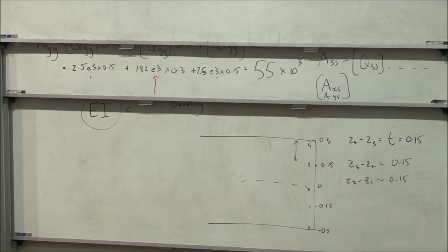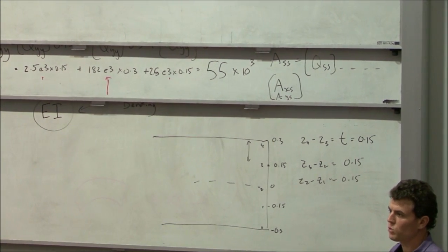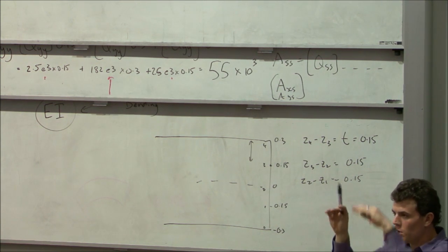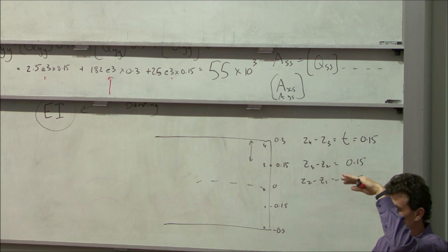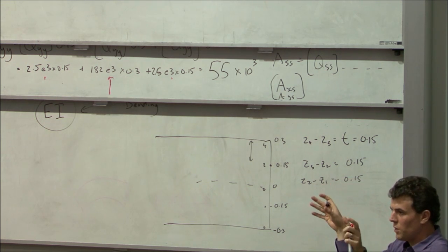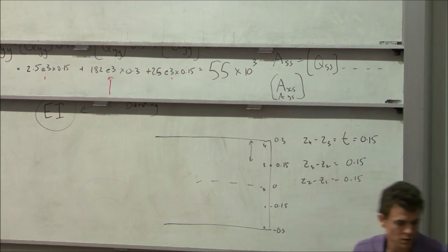So the contribution of them to the in-plane stiffness is constant. But in bending, we have to amplify the things that are away from the center. Just like when you make an I-beam, the material at the top and bottom of the I-beam has a bigger contribution to the second moment of area. With a composite laminate, the plies that are on the outside have a bigger contribution to the bending stiffness than the plies near the middle, because they're experiencing more strain as we curve the laminate.